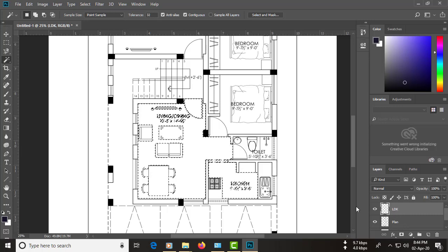And now, because I've created a new layer and I want that colors to be in a new layer, because I can vary the parameter, I can't have all the colors put up in the same layer. So I'll put the living dining and kitchen in one layer, and I'll use a shortcut, which is, now this is your color palette. What you see onto the toolbars, onto the left side bottom, you have a set of foreground color and you have a background color.